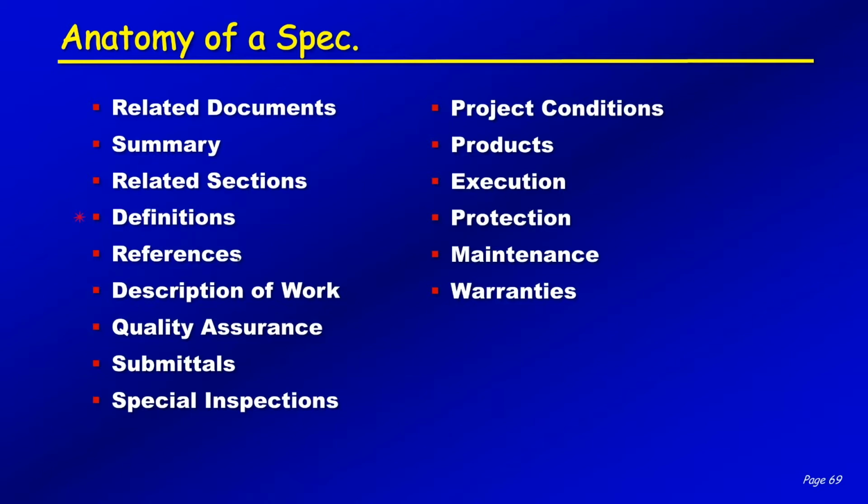that particular sections. References can bring in, we're not going to look at too many. In fact, I don't think we're looking at any specifications, but you just take ACI 301 or an ASTM number, and they'll just give you a couple of those things, and all of a sudden you've pulled in 2 inches of documents that you're also responsible for, with a 1 or 2 liner on it and a reference situation. Typically, they'll give you a little description of work. They'll tell you what the quality of the work is supposed to be, so that would be something an inspector should want to look at.